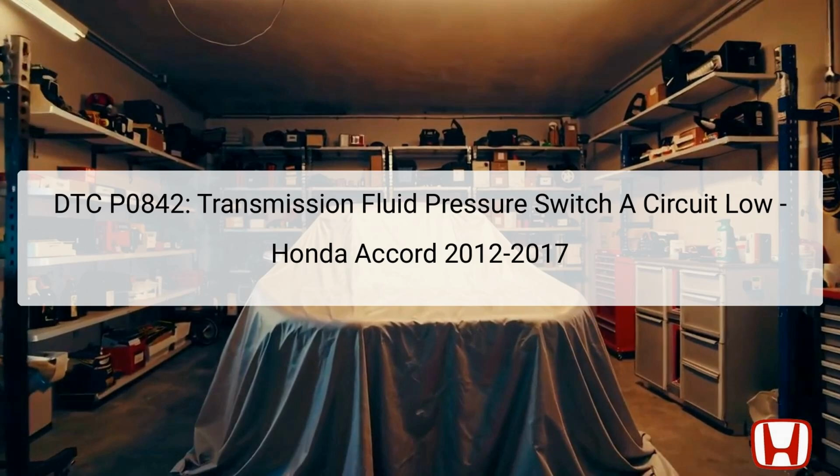The transmission relies heavily on various sensors and switches, and this issue may lead to the vehicle only being able to shift into second or fifth gear due to a fail-safe function built into the system. Identifying the root cause and addressing it promptly is essential in ensuring vehicle performance and safety. As we go through this guide, we will detail the necessary steps to diagnose and repair this issue effectively, leveraging the Honda Diagnostic System, HDS, among other tools to provide precise solutions.